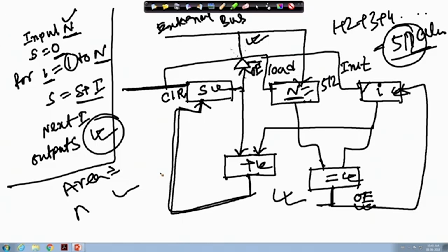But whenever we are gaining something, at that time we have to lose somewhere. So, where is the loss point? I am losing the time, that is, the total computation time of the corresponding circuit. There, within 1 clock cycle I can finish the job, but here, for 512 samples that I want to add, I have to wait up to 511 clock cycles. After 511 clock cycles, only then will I get the corresponding output.